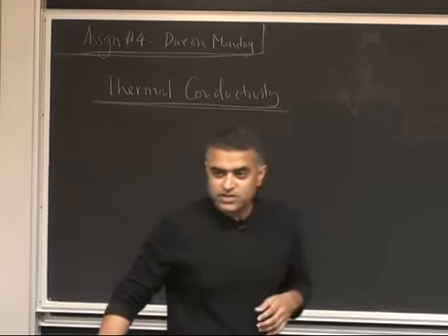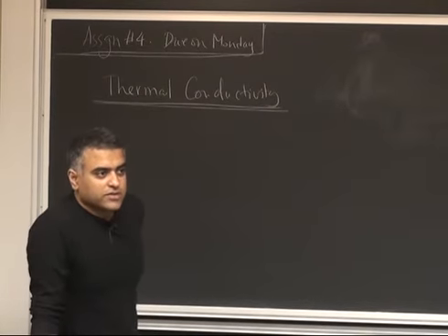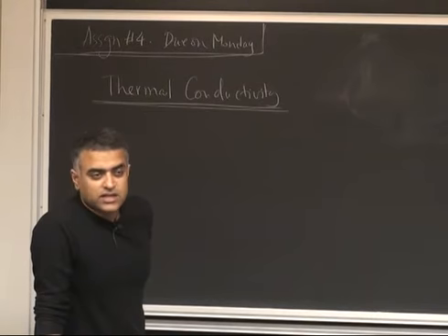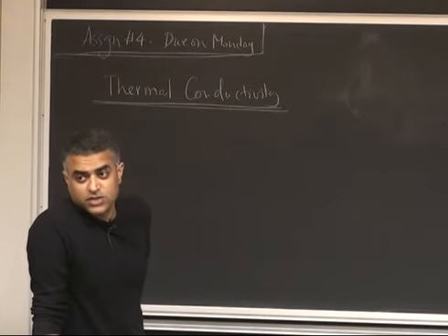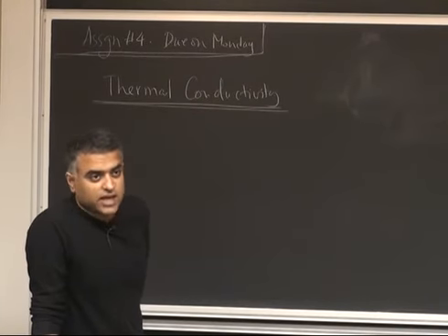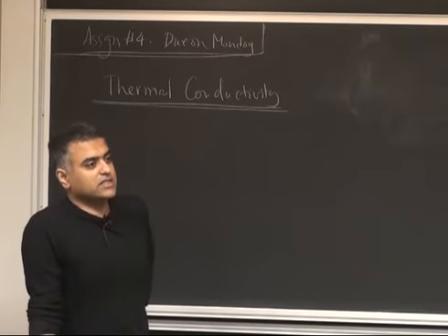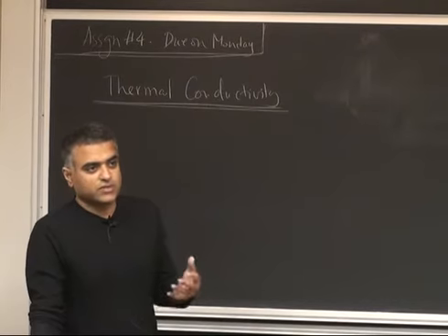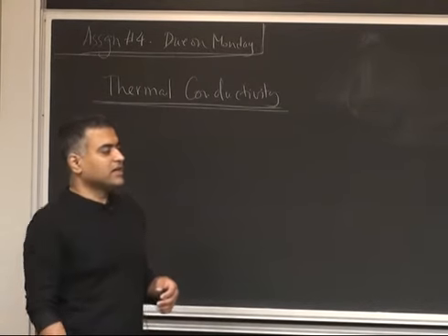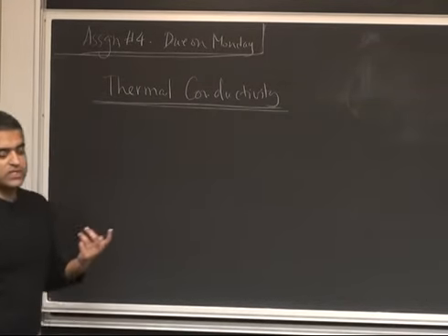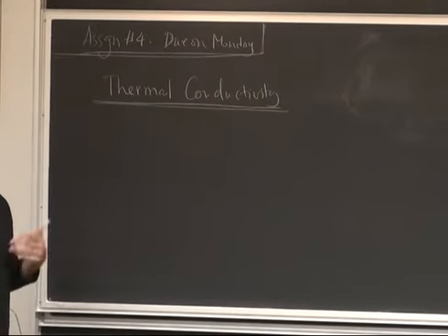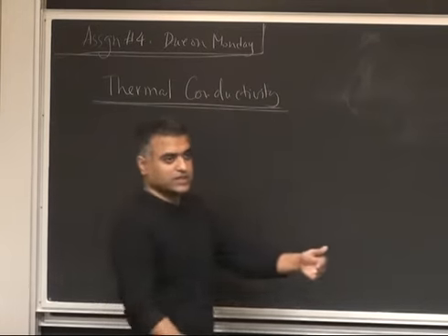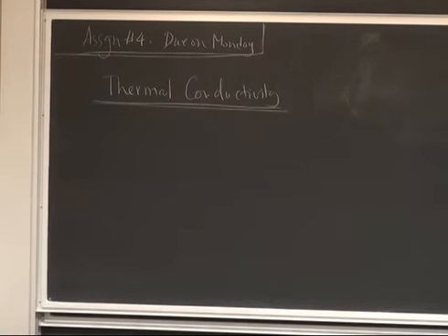What about radiation? Radiation obviously also can carry heat from one place to another, right? Which is photons, right? And it can, but inside a crystal, its contribution is minimal. I mean, small dimensions. Compared to the other two, electrons and phonons, they are much more potent in carrying heat from one end to another than radiation. And radiation, essentially, efficiency is relatively low.